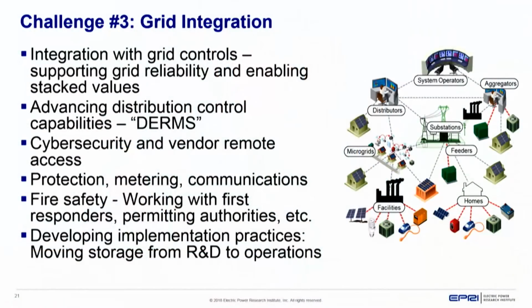The third challenge is grid integration. So similar to the analysis area, we need to be able to integrate these with grid controls so that they can support the reliability and enable stacked values. We may have heard about DERMS, or advanced distribution control capabilities. These are enabling technologies to support getting more out of, in particular, distributed energy storage systems.